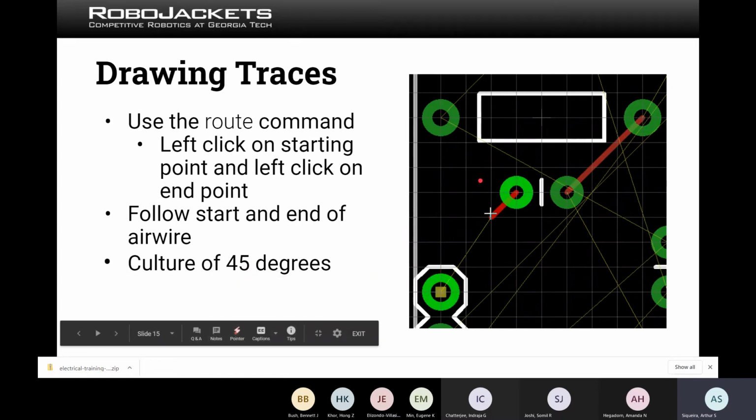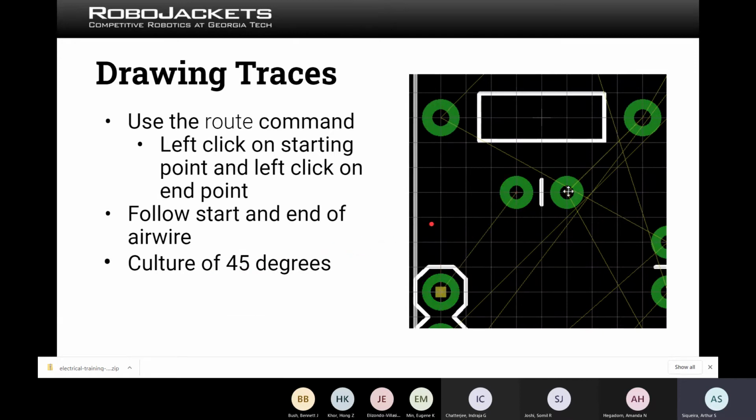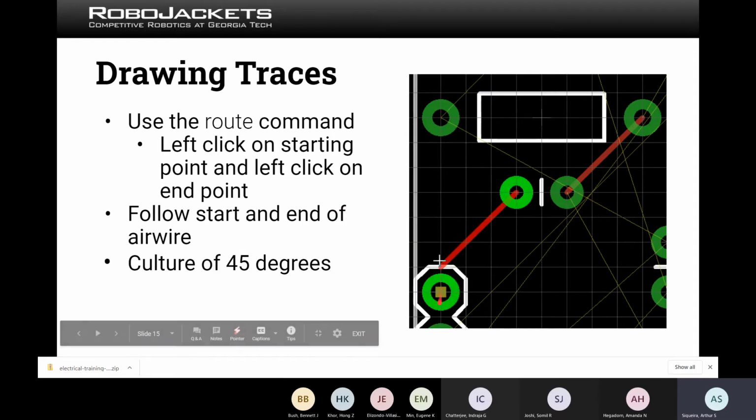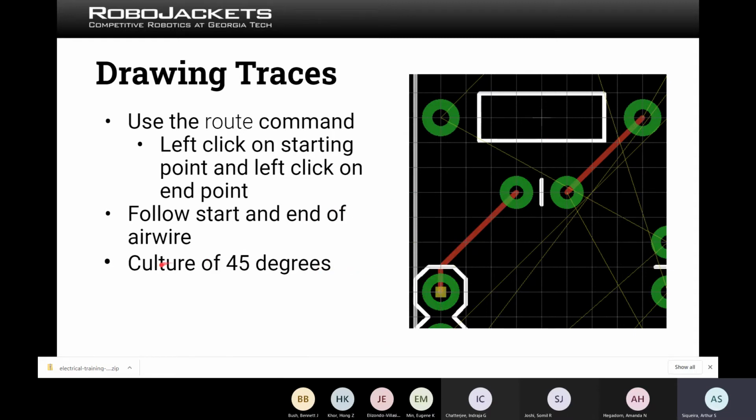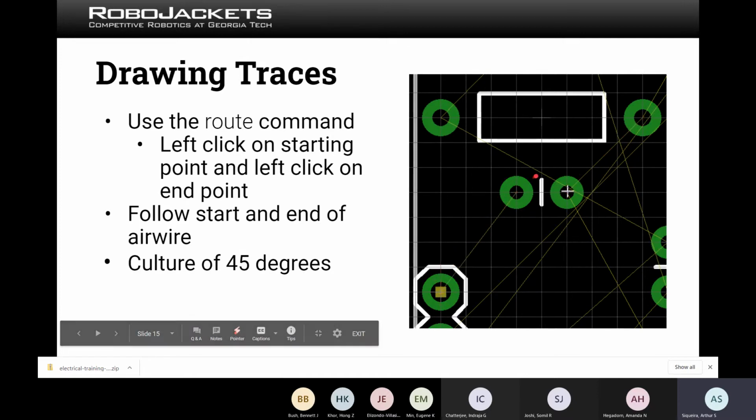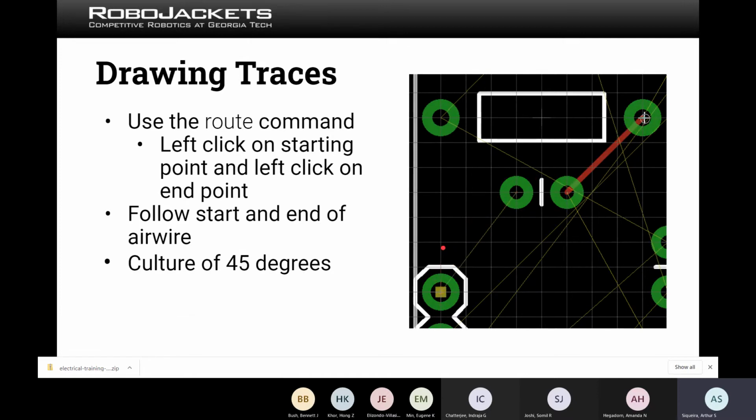Apart from that, it's quite common on every circuit nowadays to have all of the wires connecting pins on a pattern of 45 degrees. So in this case, for instance, this is just a line, but also 45 degrees. And in here, you see that every curve that we do is 45 degrees. This has been something mostly out of culture from PCB design across the years.